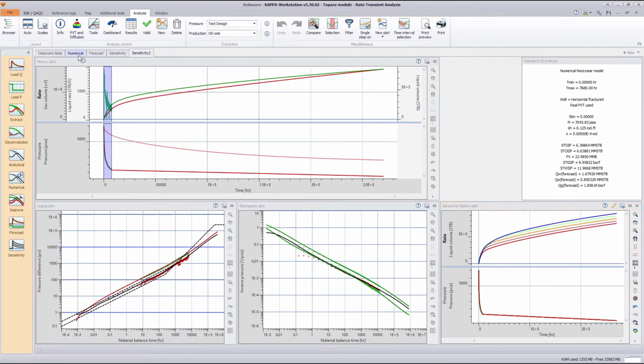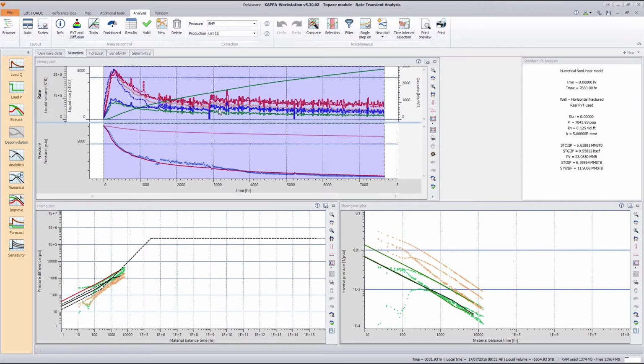And also, if we go back to the original numerical model, you can create a copy of the analysis and change your permeability, saying what if it's another value. Then you can repeat the whole process, because remember, it's never a single deterministic answer that we're looking for. It's not possible to discern the effects of different parameters unless you clearly see all the transitions. It's more complex than the conceptual models that we use, but we give you a range of models, and you can find different matches with different permeabilities and estimate the uncertainty that you have on your parameters.